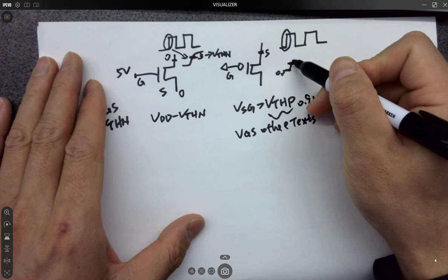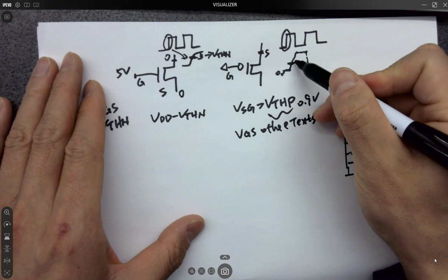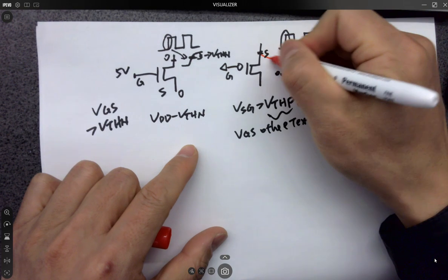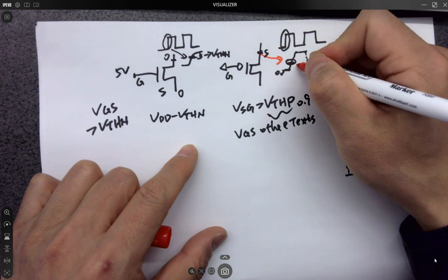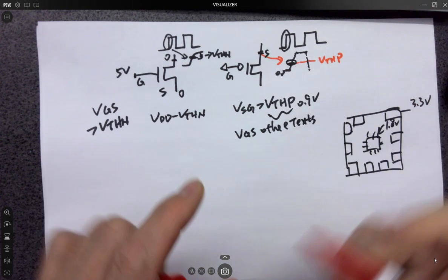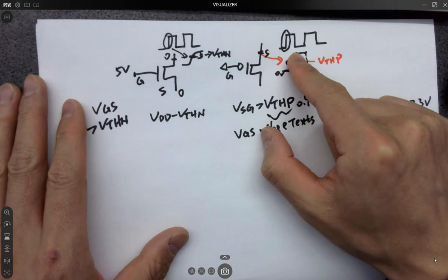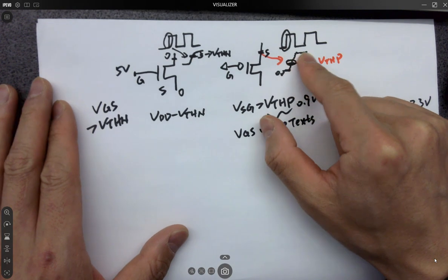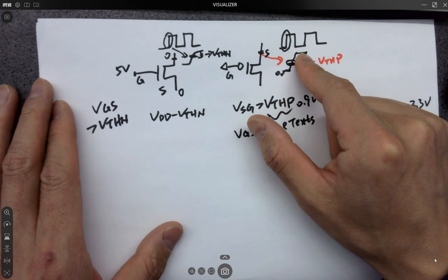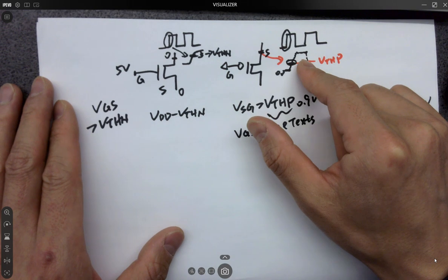In order to get all the voltages above it to pass through the gate. What is the voltage here? VTHP, right? VTHP. I mean, this is the voltage of the source. So whenever this is larger than this point, which is VTHP, it is able to pass the voltage through the channel. And you can see, since we don't have the intermediate voltages, it's good at passing ones. So PMOS is good at passing ones. Okay? Are you able to explain this in the quiz? Yeah?